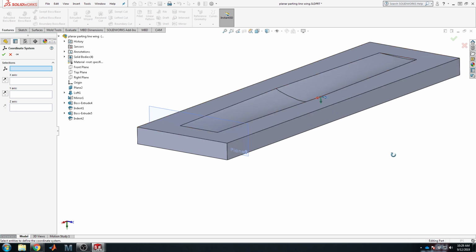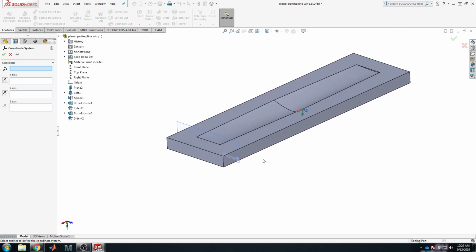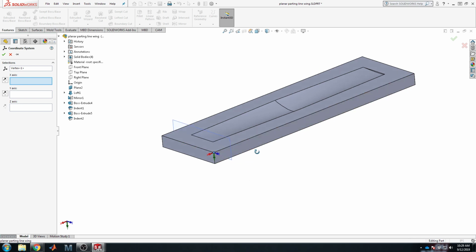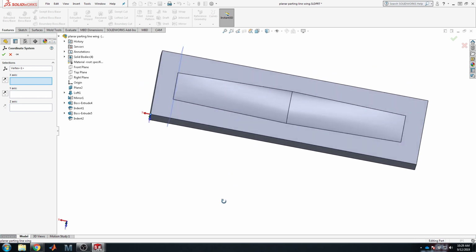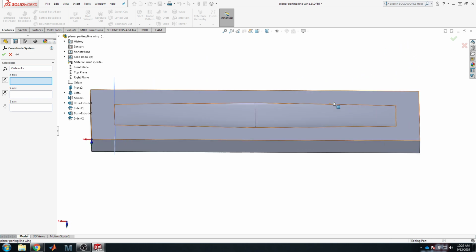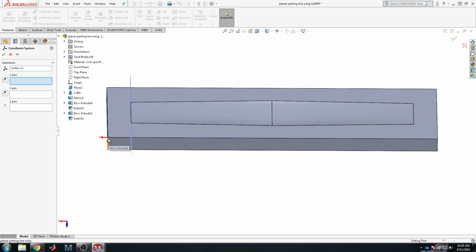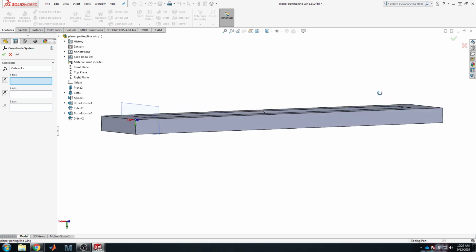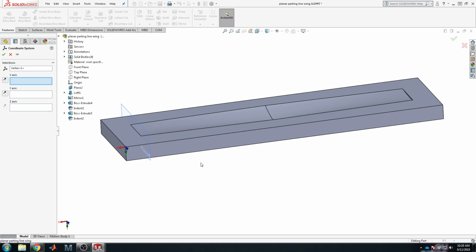The first is where you want the origin of your component to be. So which corner do you want to essentially zero your CNC machine out on? In this case, if I was going to cut it out on a CNC machine where I was facing the material, kind of as shown in the window right here, I usually try to center it on the front left. For whatever reason, that's just my habit. There's nothing more correct about that than any other path. But it's just accessible towards the front of the part and the left side. I don't know. That's where I put it.